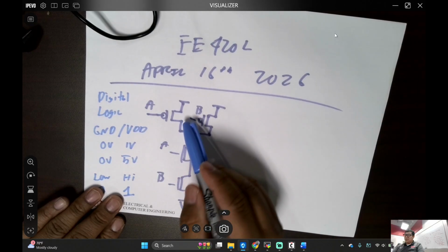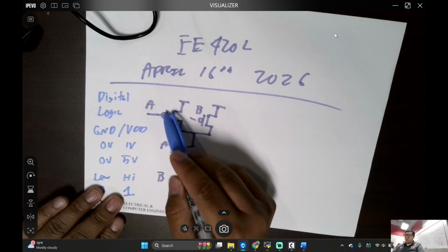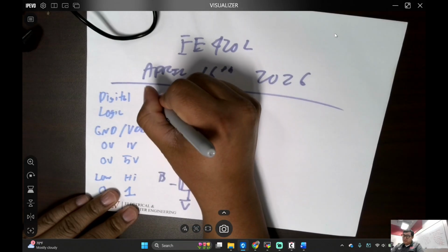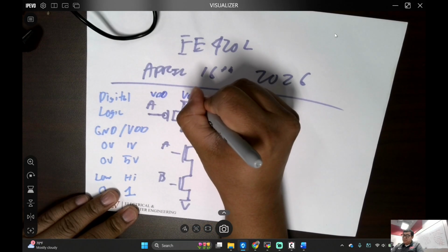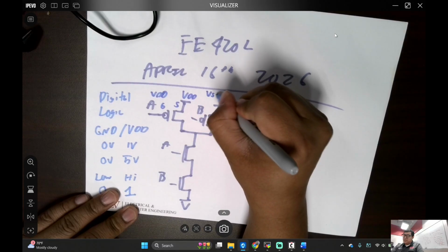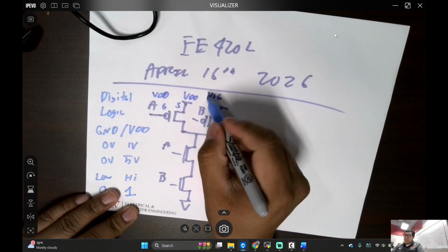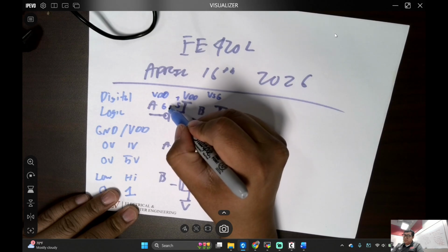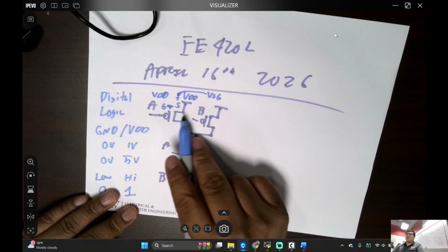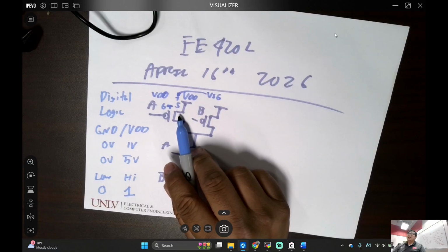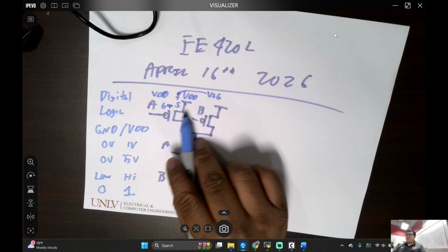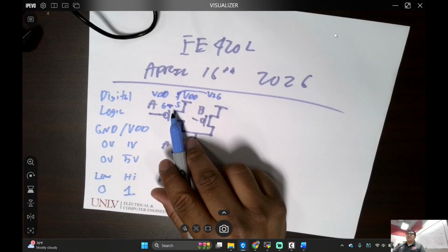And if this is a 1 and there's a 1 right here, right? If this, or VDD, if I have VDD and VDD here, and then here's my gate, here's my source, and VSG, right? My VSG plus, minus, right? If my VSG is 0 for my PMOS, what happens? There's no voltage or gate source voltage. What does that mean for the PMOS?